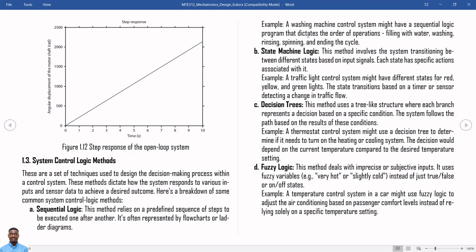If the drum is not filling up as it should, that means the water is not coming in, and it will probably come out with an error. But if the water is coming in, it will check the weight of the drum against the initial weight to tell that the water is enough, so it will stop the inlet valve, and then your washing cycle will commence.